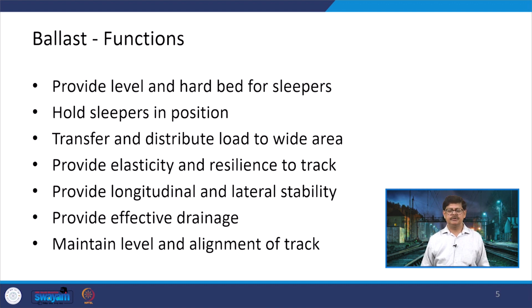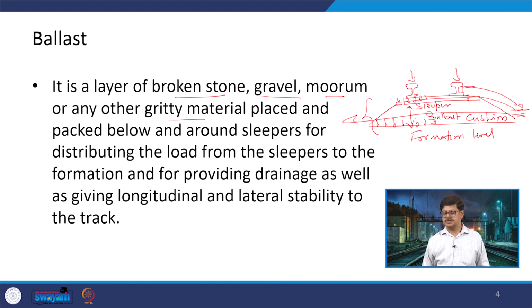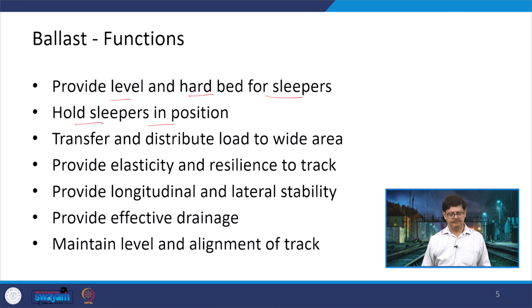So, what are the functions? Now, we have understood the things. So, on the basis of that, these functions can be very easily created. The very first thing is it provides a level and hard bed for the sleepers, because the sleepers are being rested at the top of it. Then on the basis of packing, it keeps the sleepers in position. So, there is some material which has been placed on the sides also. There is a material which is placed here, there is a material which is placed here. So, it will keep the sleeper in position. It transfers and distributes the load to a wider area, and that wider area is related to the final formation level.